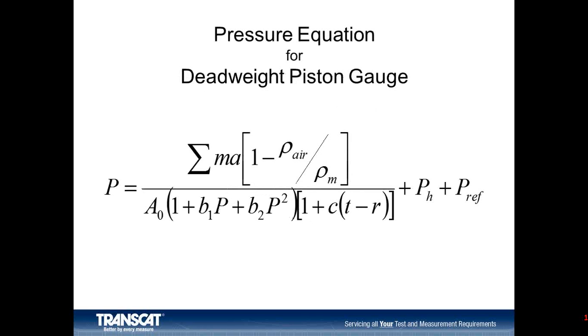And the way we apply this one is, if you look at the formula, we insert an appropriate value for each of these variables, and in this case, compute a pressure. Then for the parameter that we are investigating, mass, for example, we change that mass value by an amount that corresponds to the uncertainty in that mass. That will result in a different pressure, and that change in pressure is a direct result of the uncertainty in mass. So basically, we let this formula convert that for us.